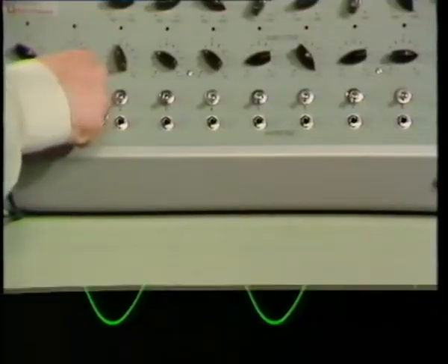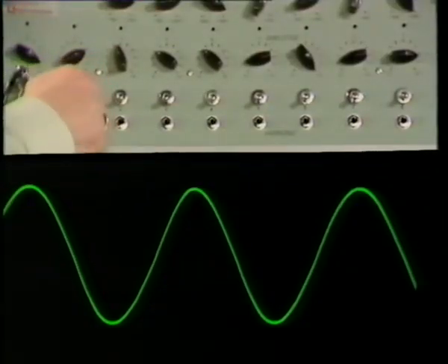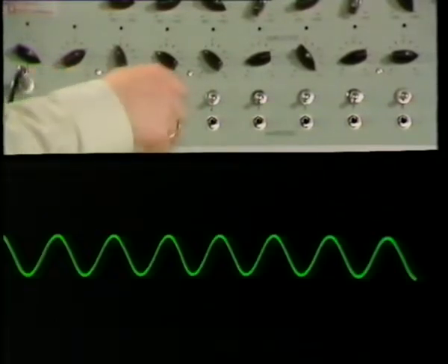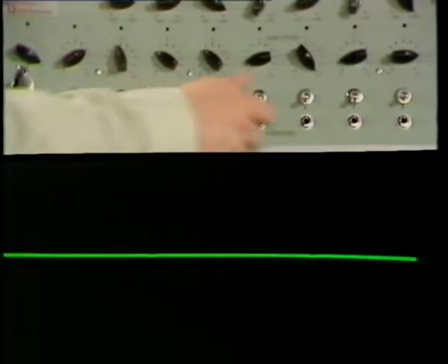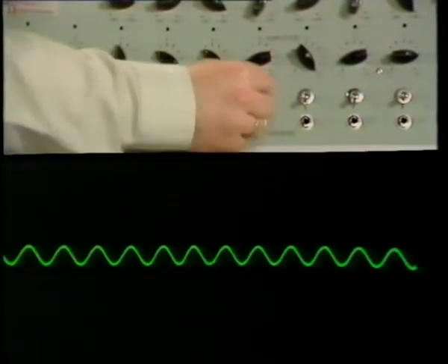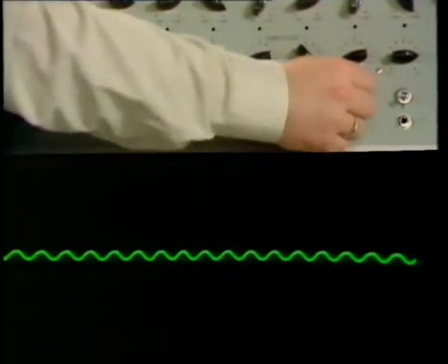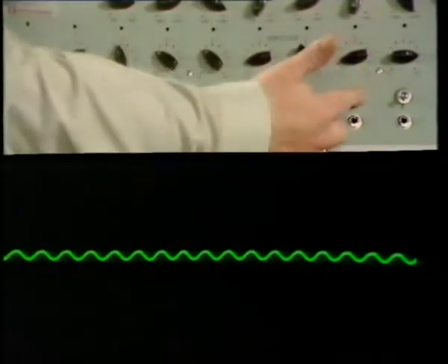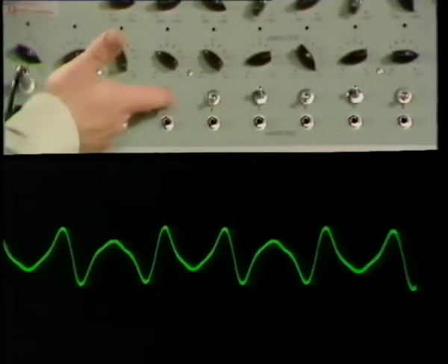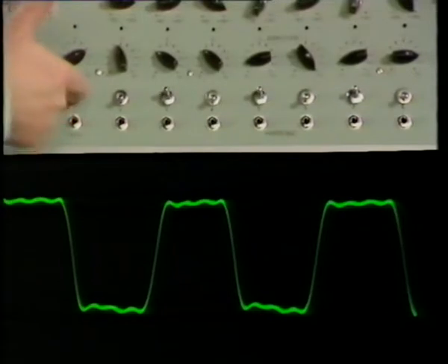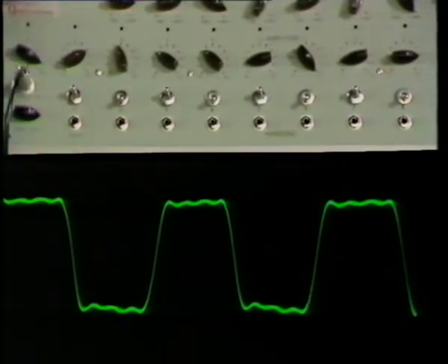And this is the equipment he used. This switch here gives me the fundamental, it's around 500 hertz. And in addition, I can get frequencies of 3 times the frequency and 1/3 the amplitude, 5 times the frequency and 1/5 of the amplitude, and 7 times the frequency and 1/7 the amplitude. This is getting quite small now, but if I now go back and add in all those other components, you can see I end up with a pretty good square wave.